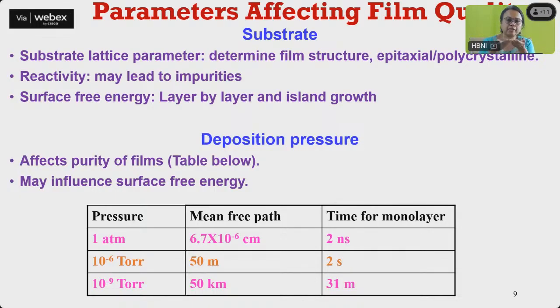If your substrate is very reactive, say you are depositing on a metal like aluminum foil, and there is reactivity, then impurities can come, or there can be unnecessary, unwanted doping, all those things can happen. And the surface free energy will lead to either layer by layer growth or island growth. This we have already talked about in the last class.